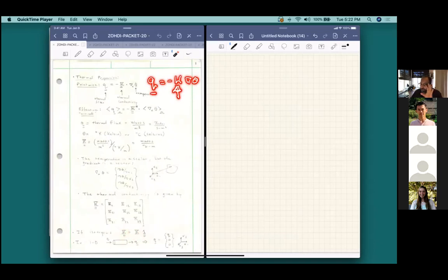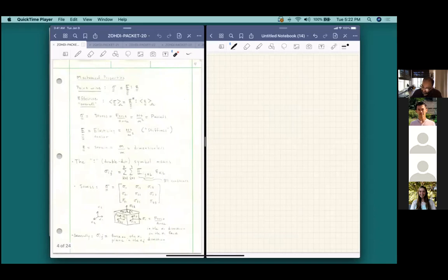So it's nearly identical to the concepts of current and electric field, except that the conductivity K takes the place of the electrical conductivity sigma C for electrical flow. Finally, the one that we're probably most familiar with by now is the so-called Hookean type of law. We're taking a very simple relationship that says you have the strain, you have the stress, and the thing that relates the two is the so-called elasticity tensor. And of course, in 1D, that's just the Young's modulus of the material.